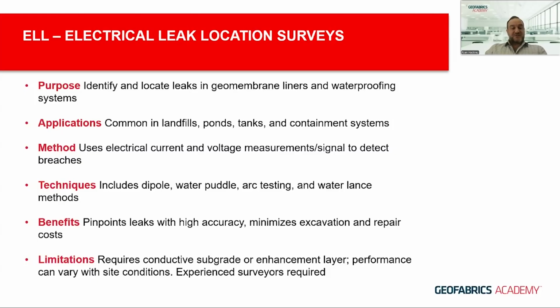Some of the limitations of the methods are that it requires a conductive subgrade as well as a conductive layer above in covered cases, or you can utilize an enhancement layer such as a conductive geomembrane or a conductive geotextile to enable that. And the performance of the surveys can vary based on site conditions.